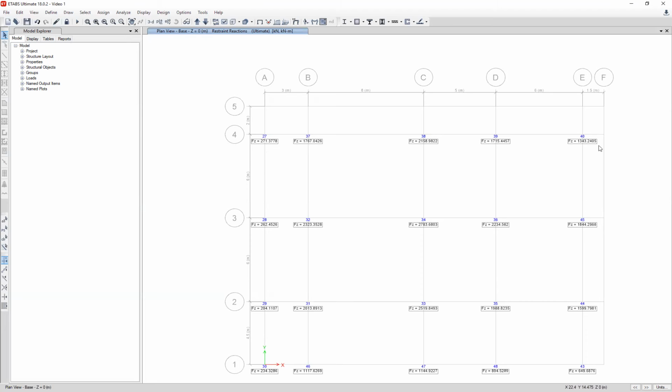You can see here at outer columns, like this one, the spacing is not that much. You have 271 kilonewton. However, middle columns, because they are carrying load from all dimensions, the area is more, so you have a bigger value, 2,783, and so on. You can use these values to make initial sizing of your columns again, and re-change the column sizes in your model to have a good design. Because initially we have to put some dimensions of the columns, and you can refine them again if they are not suitable based on these values.